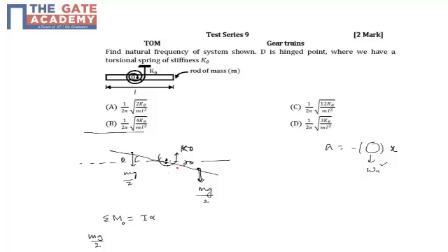This entire half is L by 2, and mg by 2 acts at the center of each half, so this distance is L by 4, times the vertical, which is cos theta. So L by 4 cos theta is the moment due to this right side mg by 2. This mg by 2 on the other side will be negative, since it's anti-clockwise and we are considering clockwise positive.